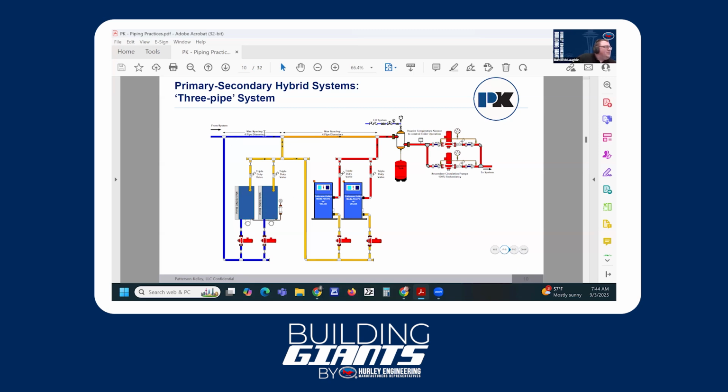But even if we put multiple boilers, we're still following the same basic principle. We've still got a primary boiler loop here and a primary boiler loop there, right? And so we're using the outlets from our condensing boiler as the return for our non-condensing boiler. I want to get to the next one. Sometimes even you can see here, we've got triple duty valves. So we're balancing this flow through here to make sure we have the flow we'd like. But you can even do these primary secondary setups with a reverse return as well, just to make sure you have flow balance through the equipment.